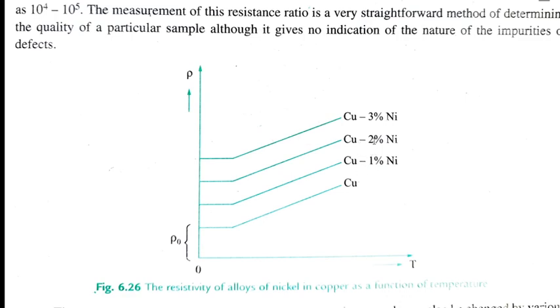As the percentage of addition of nickel increases, the copper nickel graph is shifted up, that means residual resistivity increases by steps of identical jump, and this is proof that the first step of Matthiessen's rule is giving the segment independent of temperature. In this portion you can see the temperature region is constant, and that is what we are highlighting over here.